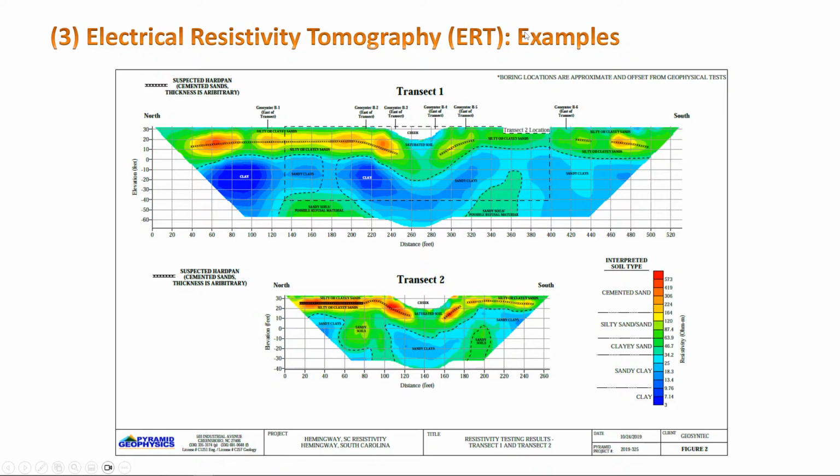Basically, in electrical resistivity tomography, you build this 2D image, this 2D transect, by doing profiling and sounding, and that's what I told you. Remember, you don't only use four electrodes. The instrument we have, which you will see in the field trip, has 48 electrodes. It has four cords. Each cord has 12 electrodes. You can hook up 12 electrodes to each, and then you can hook those 48 electrodes to the machine.